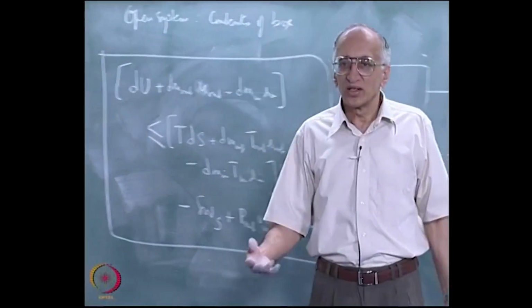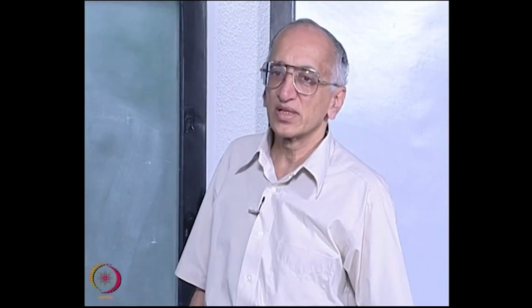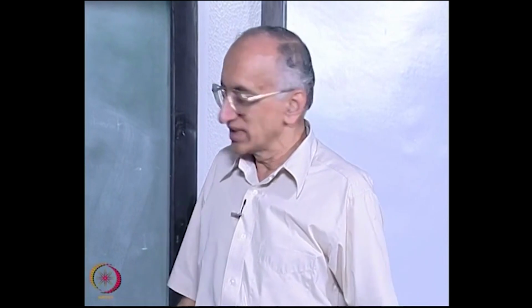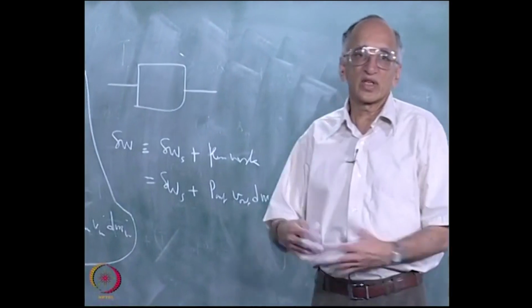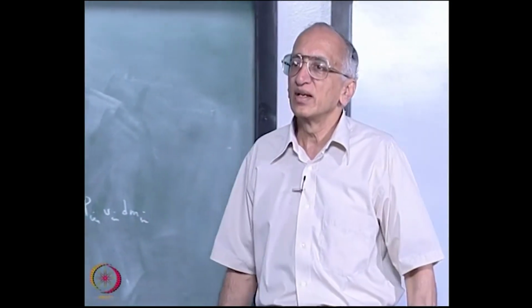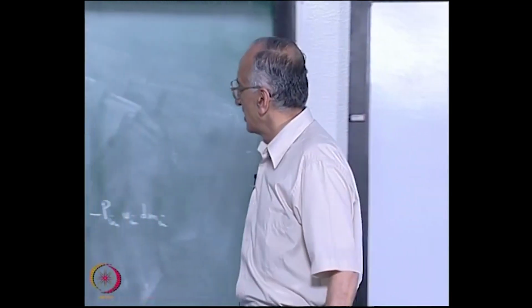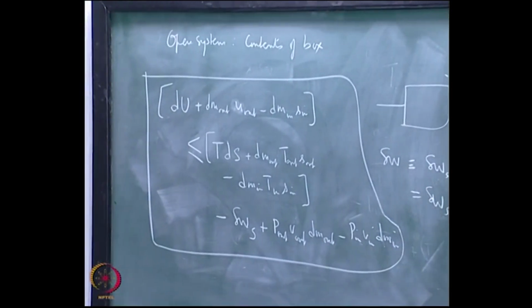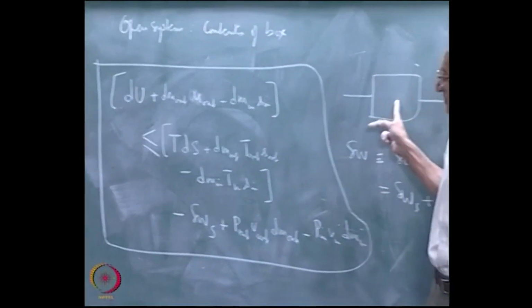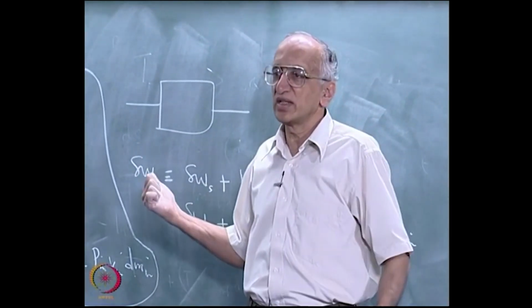Then I will start from this and show you that at steady state, basically in any process in chemical industry you are only interested in what happens at steady state, because even if you are working a mechanical turbine, you are not going to operate it for half a second, 2 seconds, so on, you are going to work it at steady state and ask how much work you can extract from it. At steady state the mass going in will be equal to the mass going out, dm out and dm in will both be equal, and nothing will change in the box.